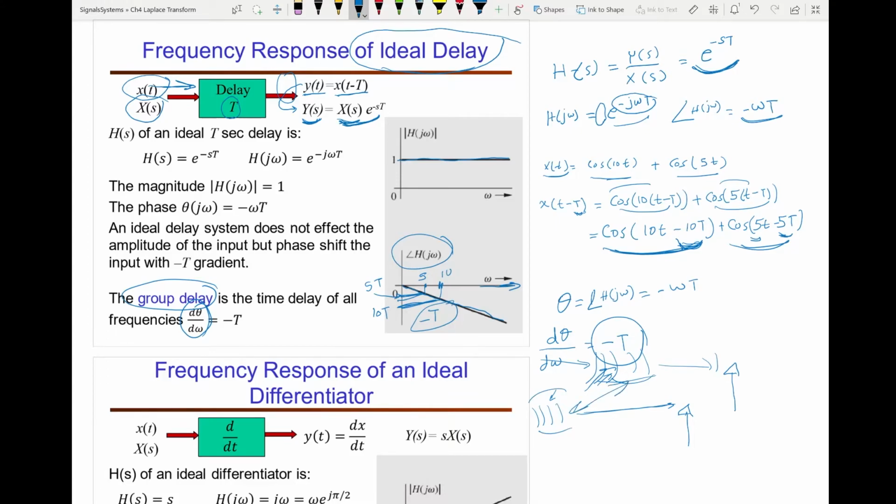When you align them and you add them up, the noise looks like this, and then the other one came maybe delayed a little bit, but it has different noise. So if I delay this one so it's aligned with this, then I add them up, I will constructively enhance the signal that I want to hear. And noise, because it's so random, when you add them up, it's like averaging noise, so the amplitude will be less. And that's one application where we use delay in communication.